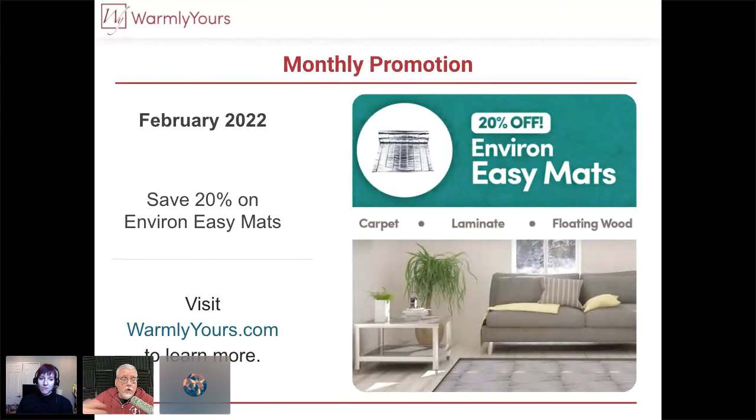And you simply roll them out. You roll the non-heating lead up the wall and put a thermostat on it. And it literally can take you 30 seconds to install like 30 square feet. It's very, very quick when you're heating the correct thing. The thing to keep in mind about Environ is Environ never attaches to anything, and nothing ever attaches to Environ. It's a floating installation.